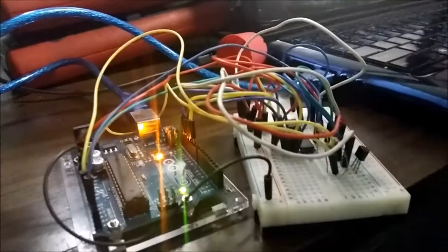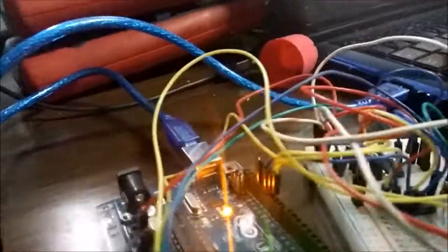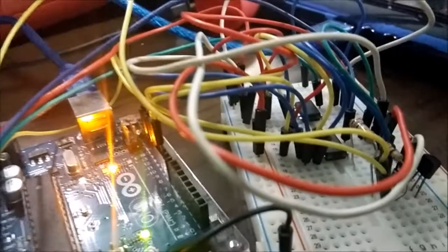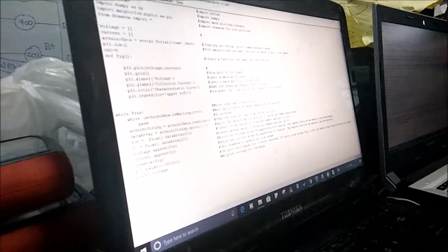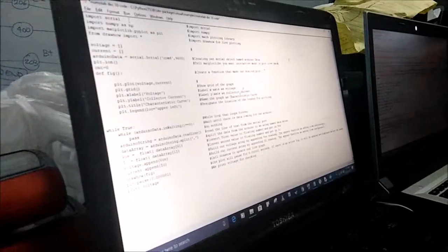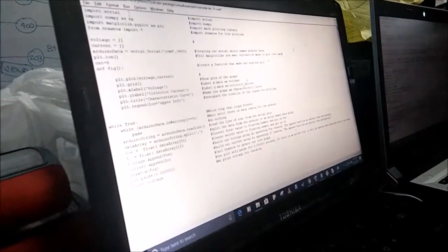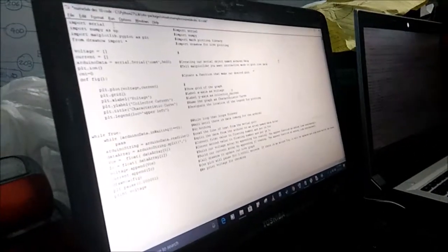To obtain the IV output curves of the BJT from the implemented curve tracer, it shall read the voltage drops at the transistor when separate voltage sweeps at the base and collector are applied by using a DAC converter, which have been mentioned a while ago. We'll explain how we did the live plotting and how we get our data from Arduino.